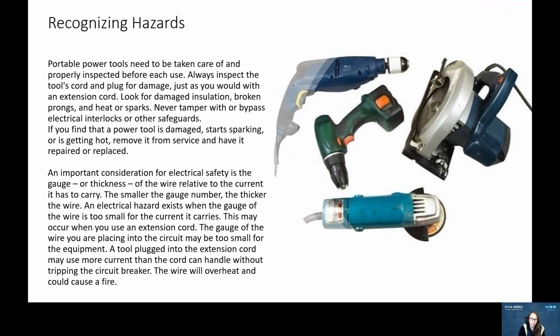Portable power tools need to be taken care of and properly inspected before each use. Always inspect the tool's cord and plug for damage, just as you would with an extension cord. Look for damaged insulation, broken prongs, or heat and sparks. Never tamper with or bypass electrical interlocks or other safeguards. If you find that a tool is damaged, starts sparking, or is getting hot, remove it from service and have